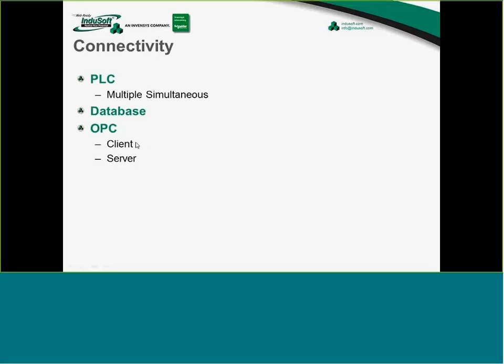Now, InduSoft by default is a client that can talk through anybody's OPC server that's compliant as well. And we communicate as clients as OPC UA, OPC DA, which is probably the more common one that's out there now, at least in the United States. UA is picking up a lot of steam throughout Europe and throughout the U.S. as well. We also support OPC .NET and OPC XML as well.